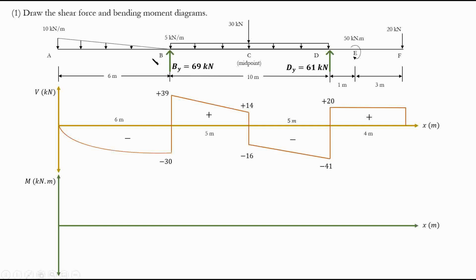Well, you say, okay, we have a shear here, and we have a moment. What I'm going to do, I'm just going to take the moment. So let's say we cut the section here, and we took this out. And we have shear and moment. You take the moment about just to the left of B, just about where you cut. And I will emphasize this point again and again. Always when you're cutting a section, take the moment about where you cut. That is going to help us immensely in avoiding extra calculation.